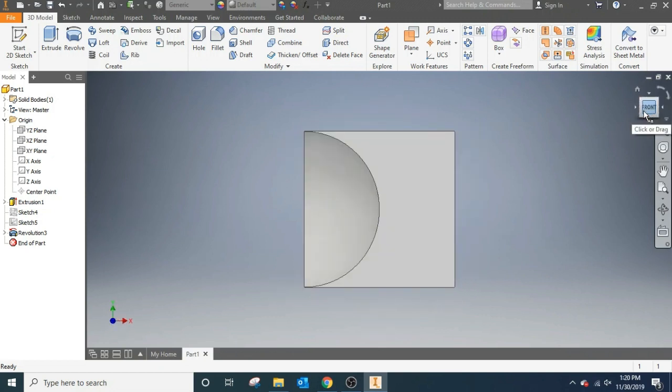You can either use it to make a 3D shape, or you can use it to subtract from a 3D shape. And again, you either have your axis as part of your sketch, or it can be outside of your sketch and just changes the type of shape that you're going to be making. Either one solid closed shape, or you can make a shape that's circular with a certain cross section with a void in the middle. So that is the Revolve tool.